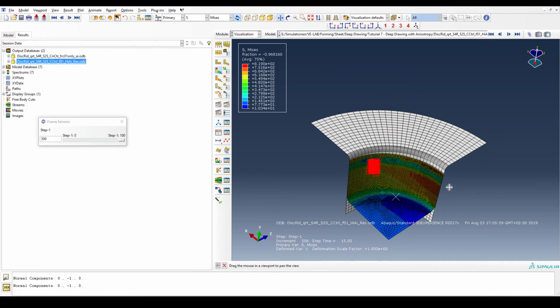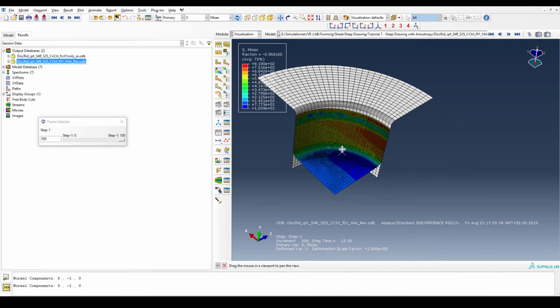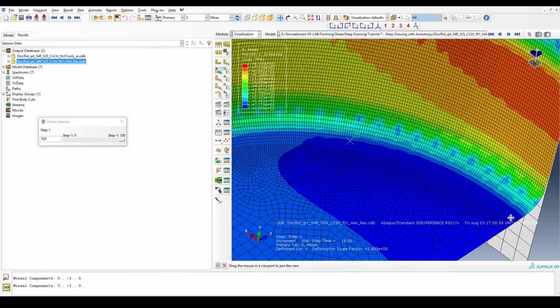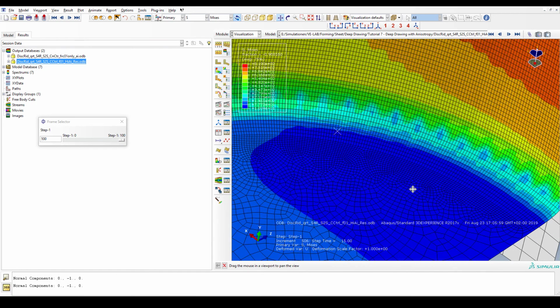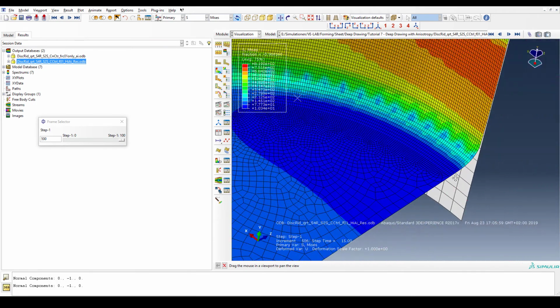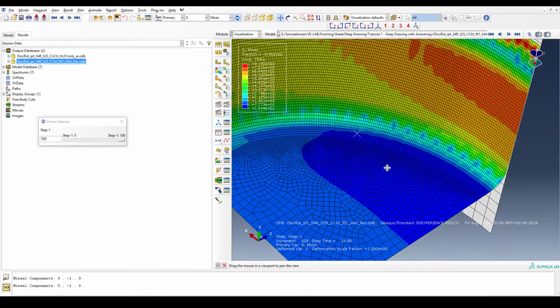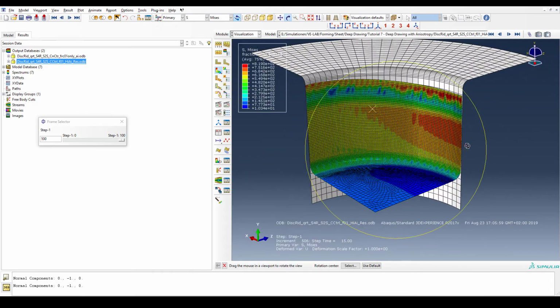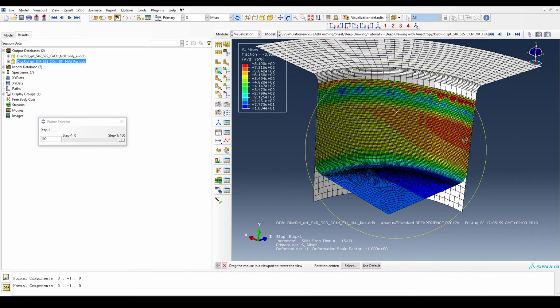And here you can also see what I talked about. You can see that the segment where the radius is being formed underneath the punch is part of my axisymmetric mesh. So maybe it's a close call here. I could have extended the axisymmetric mesh, let's say up to here a little bit, to make sure that it really is an axisymmetric response if I'd use an isotropic material model.